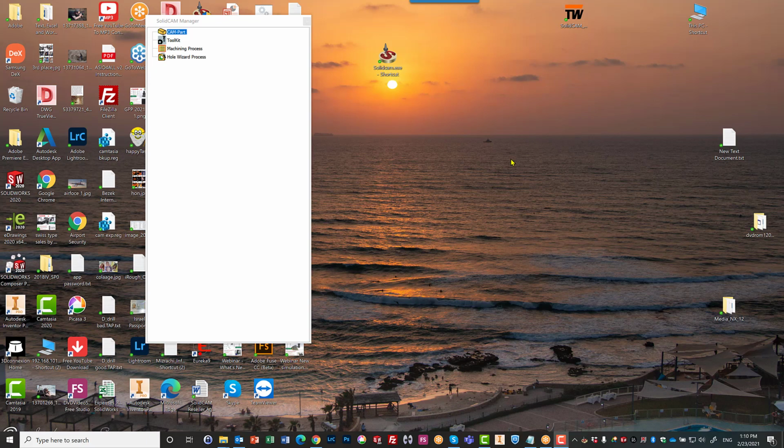There are times when a programmer would have a program that he had done, and he sends it to the shop floor. Now, there are times where the shop floor, the actual machinist himself, may be a little more experienced when it comes to the feed rates and the spin rates on the part itself, or maybe cases, for example, there's a night shift and a tool may have broken and they have to put in a new tool, and the tool is slightly different than it was before, and you may need to make minor changes in the program itself.